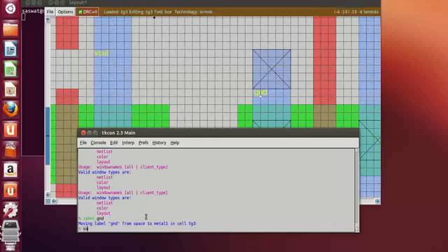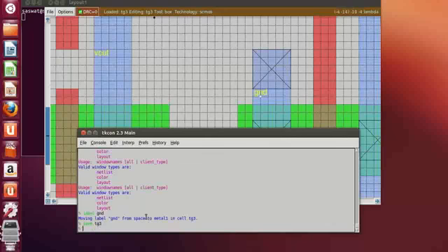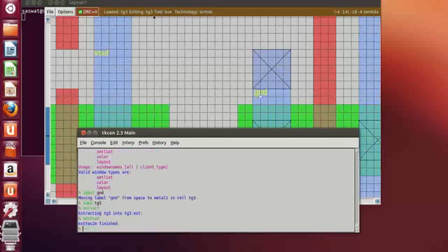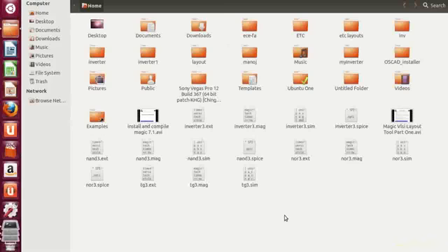Okay, now I want to save TG3, and next is to extract. It's extracting TG3 into tg3.ext. So my ext file has been created. Next is to convert this .ext file to .sim file. So extract to sim. Done. .sim file generated. If you want to see, you can go to the home folder and you can see my .mag is my magic file, the layout, .ext, .sim.